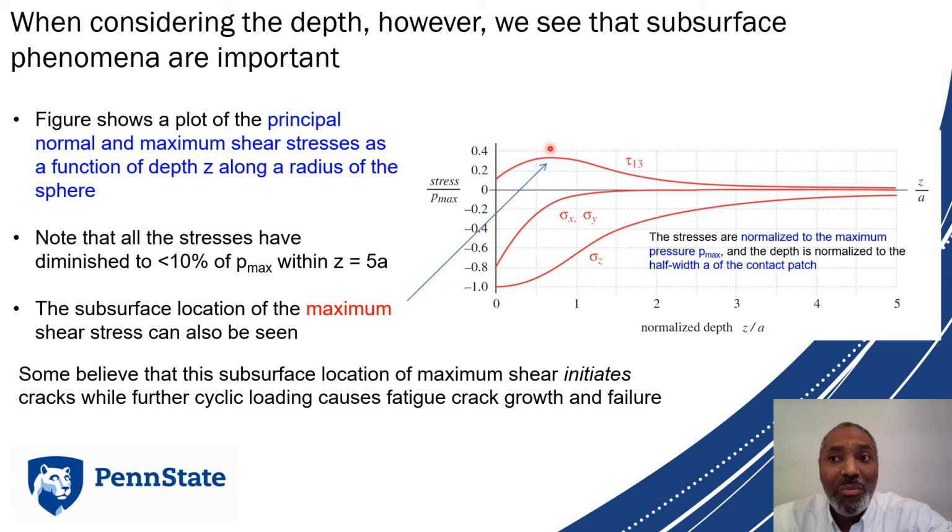What also happens, if we have this beginning of a shear failure, and then we add on to that these normal stresses which act at that point, if this is something that's rolling, meaning that point of contact gets loaded, and then it gets rolled over, it gets unloaded, but then if it rolls back to that same point, or if there's something that's loading it, releasing, in a normal stress fashion, here compressive stresses, then that can lead to fatigue crack growth. And we have this fatigue failure phenomena that's added on to our initiation of failure due to shear.